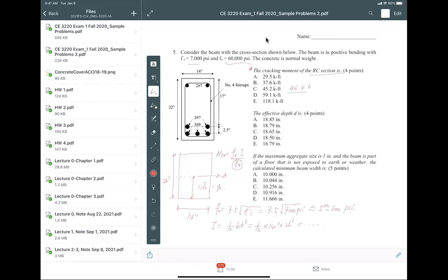46.2 kip-feet. Now, I think that might be an error from when we changed the section sizes, because before, I believe, it was 20 inches or 24 inches, I can't remember. But in the exam, if you have a situation like this, pick the closest. I added that to the exam that you see tomorrow, just this morning, matter of fact. So among all these answers, C is the closest. So we'll select C.